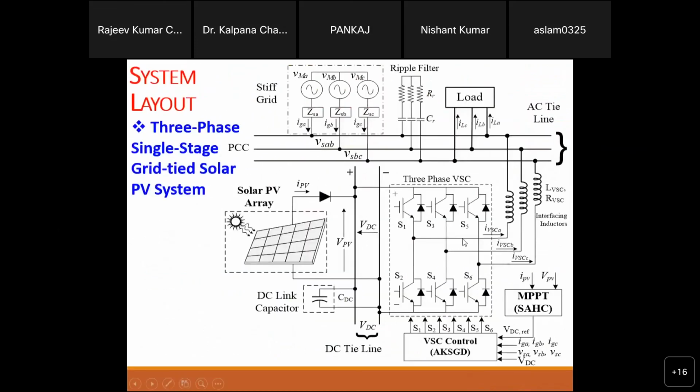For example, in the night time, this converter and this capacitor, that's it. This capacitor and this converter will generate those nonlinear currents only. The PV panel and this diode, and if you have the DC-DC converter, will not be in operation. It is just like a D-STATCOM. If you look at the D-STATCOM structure, what is that? It is only the filter, the interfacing inductor, and this VSC, right? So this is a D-STATCOM. If you remove the panel here, it will look like a D-STATCOM, right? So in the night time, it will act like a D-STATCOM or a STATCOM also.